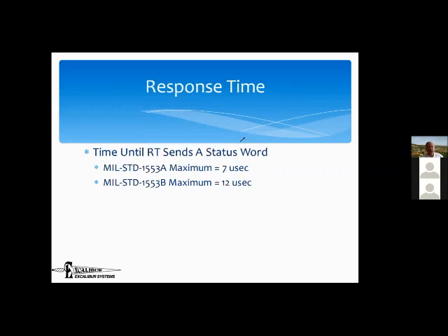Okay, response time, we saw what it is. Response time is the amount of time that the RT has to respond following either a transmit command or a receive message, including the data. Now, the original spec of 1553A put it at 7 microseconds. 1553B expanded that to 12 microseconds.